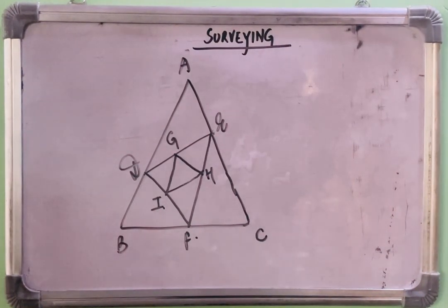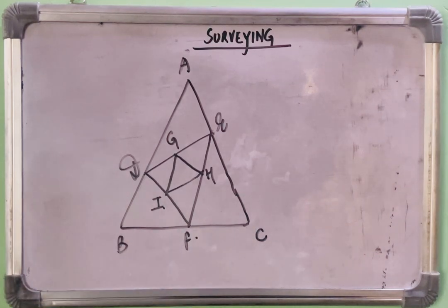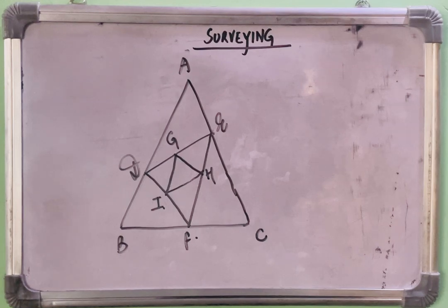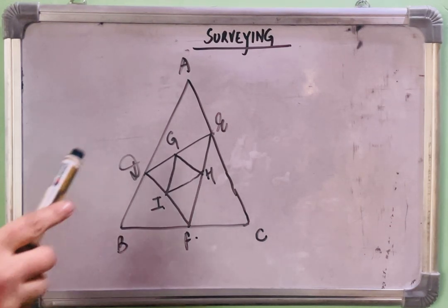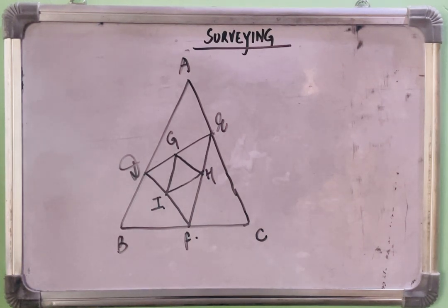So let's illustrate the first principle of surveying, that always work from whole to part, by this diagram. First, we'll establish the precise position of point A, point B, and point C, right? With very high standard of accuracy. Thereafter, this forms a large main framework, and these are the control stations. Thereafter, we can establish the position of point D, E, and F by relatively lower standard of accuracy. And thereafter, we can plot the small triangle GHI by even still lower standard of accuracy, right?